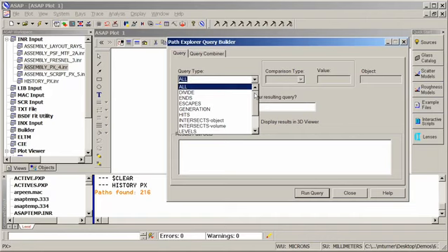What queries allow us to do are isolate particular subsets of those 216 rays. For instance, I can go through and look for those rays that divide at a particular surface or object within ASAP. Similarly, I can look for rays that end on particular objects or rays that escape the system. These would be rays that did not end on an absorbing surface. I can sort the rays by their generation. The 0th generation are the first rays that come from the original source, and then each level of splitting and/or scattering will create a subsequent generation.